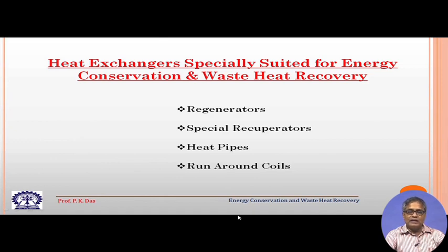So, that thermal energy which was stored will be taken by the cold stream. Again the hot stream will pass through the storage material. This process will continue and we will get heat exchange from the hot stream to the cold stream via a storage medium. So, this is the working principle of a regenerator and there are different kinds of regenerators.